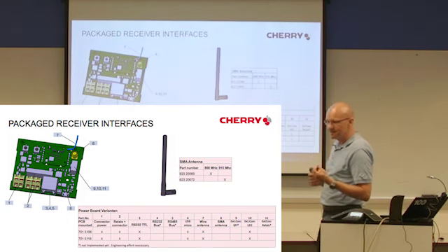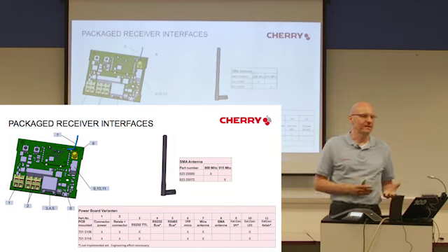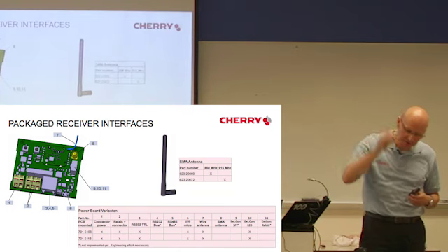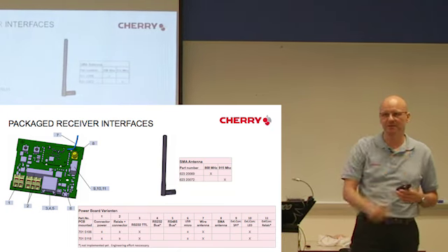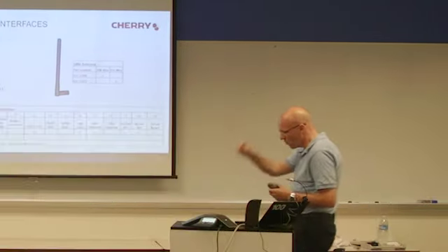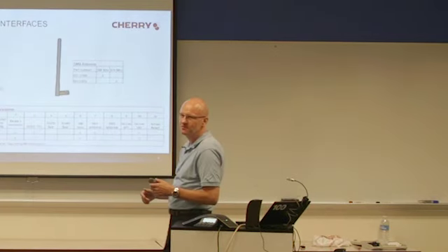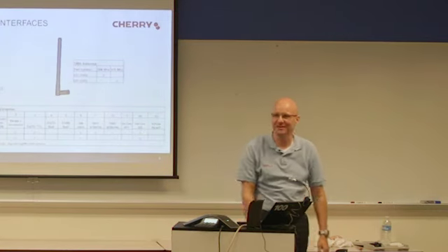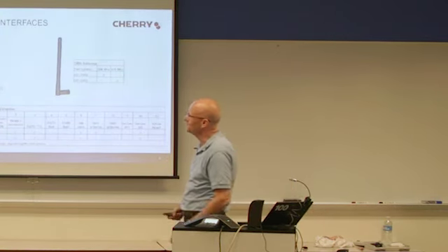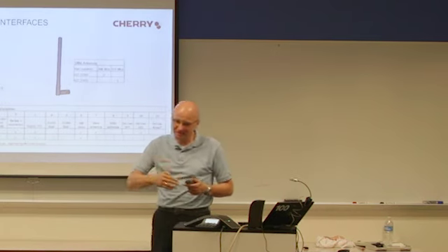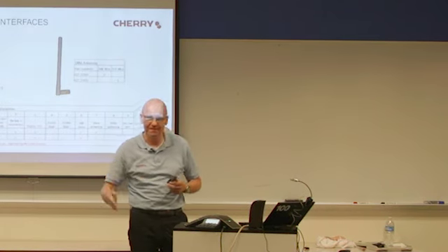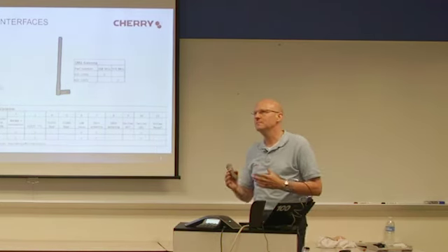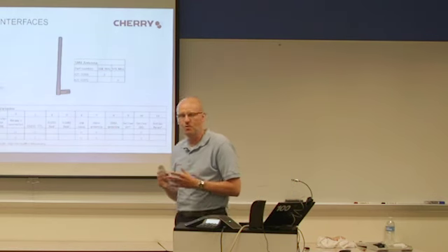The unique ID is an absolutely unique identifier. Every switch we're producing gets an absolute unique identifier in the production. So we started with the number 1, and the second got the number 2, and meanwhile, I don't know, we are at number 3,000 or so, all the engineering samples we made. But when we start in production, every sender gets a unique ID. And the unique ID data is 32 bits, 4 bytes.